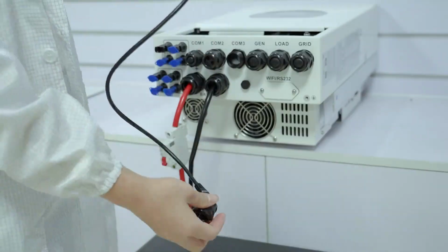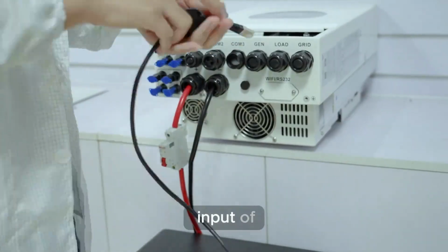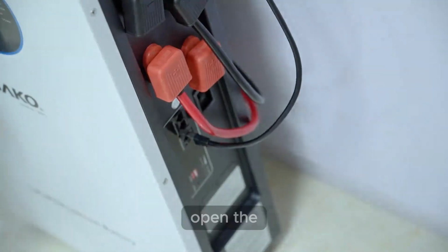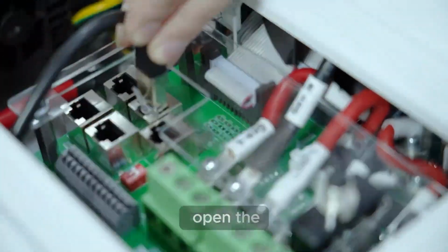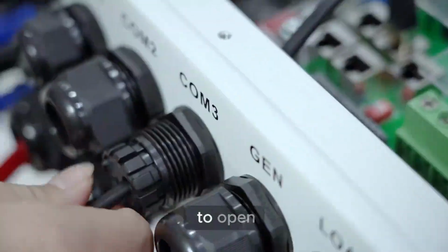Step 4. The AC input of the inverter is correctly connected to the mains. Open the lithium battery start switch, and then open the inverter start switch to turn on the inverter.